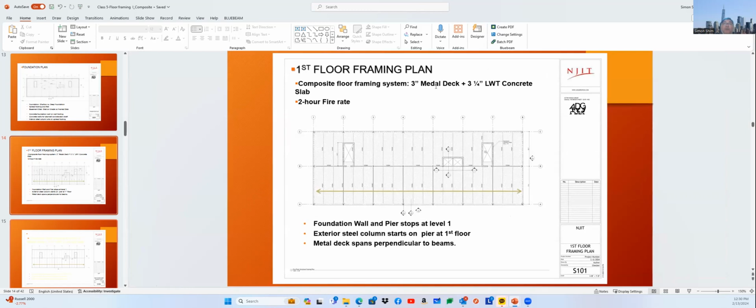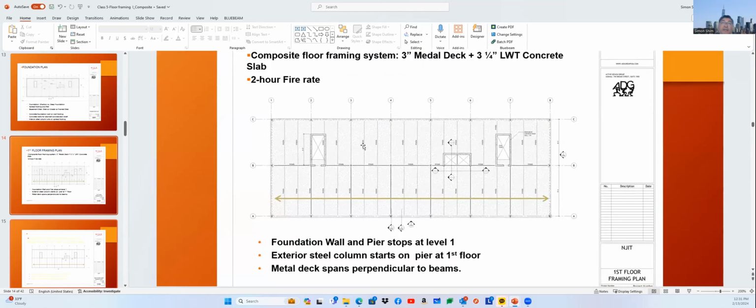Typically, you guys can use either of two slab systems. One is a 3-inch metal deck, which usually supports the concrete weight and floor live load over your slab span, which is 10 feet. Structurally, 3 inches is pretty common for 10 feet with office loading conditions, but sometimes 2 inches is also used for a shorter span with less loading.